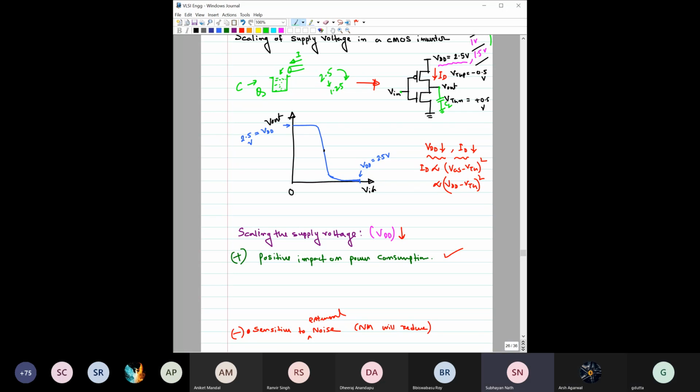Sir, actually the R is changing; it is increasing. So we're looking into the drain side of basically the NMOS portion. We know that the R will be roughly R naught. Like, there's a huge expression, but it is proportional to R naught. When ID decreases, R naught increases. So you are saying that the resistance is also changing. Yes, sir. Okay. So the resistance is also changing.